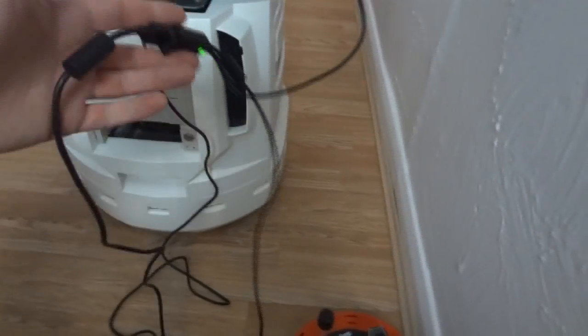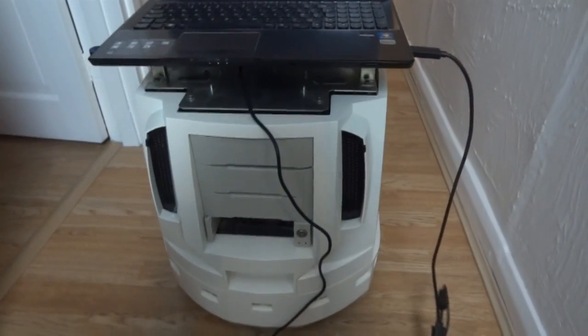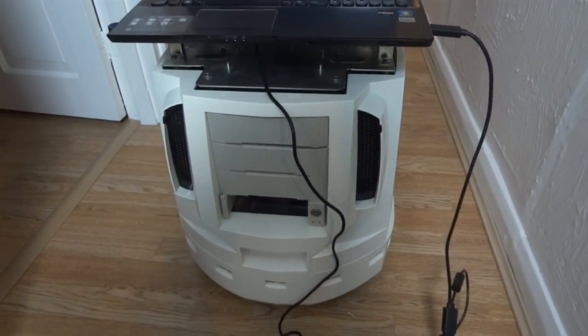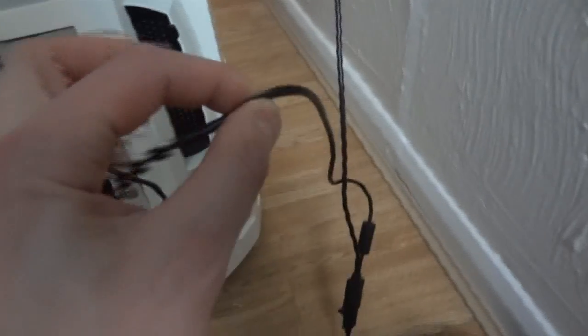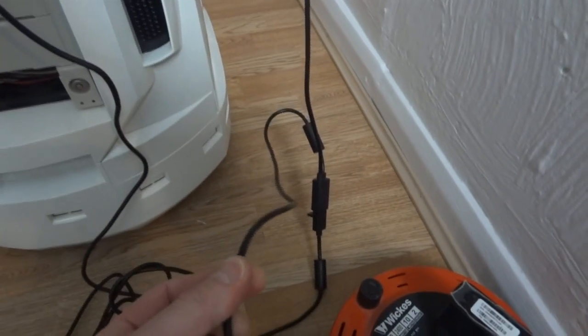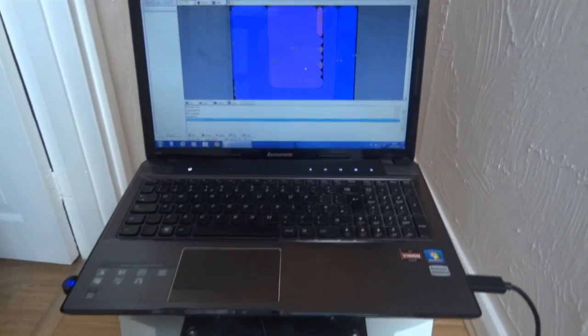So that's not bad on the whole, because the robot's actually got a 12 volt battery and regulated power supply on board. I've got another one of these power supplies, and the plan is to just cut the cable which would go to the mains adapter providing 12 volts and wire that to the 12 volt battery to power the Kinect, and that way it won't run the batteries flat of my laptop, which is going to ride on top, powered by its own battery.